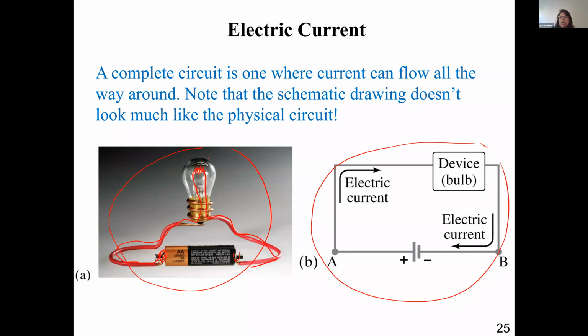Okay. So to light it up, there should be a current. In addition to that, there should be a power source, right? And in addition to that, there should be a closed loop. These are the three requirements that you should have. You should have current. To have a current, there should be a power supply or potential difference. And there should be a closed loop to have work done in the circuit.